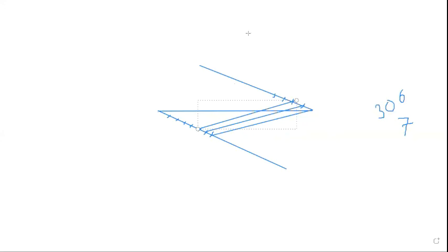So for this, what we'll do, we just draw a line of 30 millimeter. Then at this point, we draw a line at 45, less than 90 degree, and by using the compass, taking any measurement, we just divide it. Suppose it is 7 equal parts, so we divide it into 7 equal parts, and first last point to last point we join it, and then we draw the parallel line. Okay, so the figure is shown very well. This is the way to divide the line. Clear? So this is the tutorial lecture.